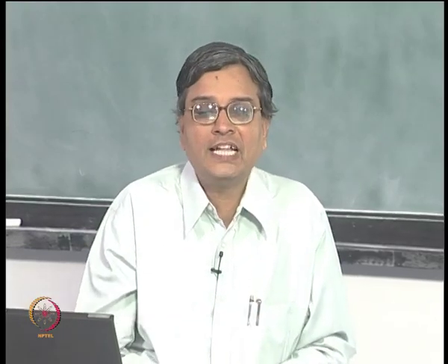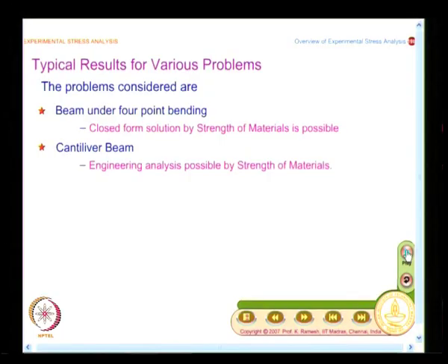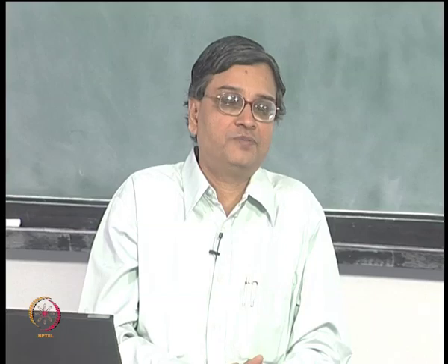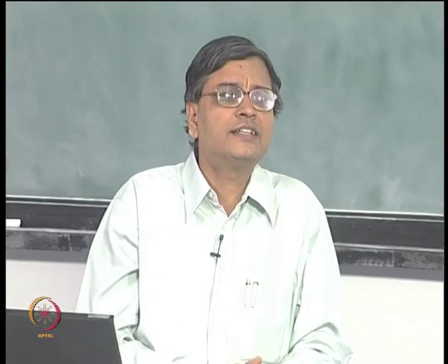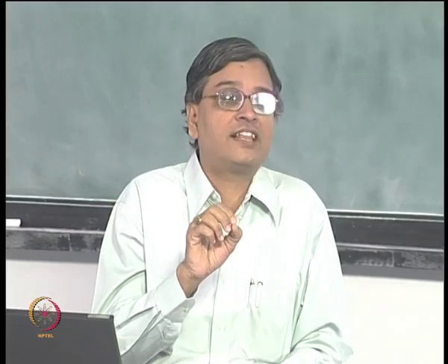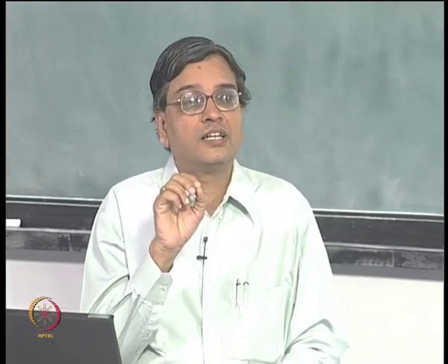Okay. Then the next problem is cantilever beam. Why I have taken this is, see, in a cantilever, though you apply flexure formula and so on, you actually have shear which makes the planes not remain plane before and after loading. Because shear effects and bending effects are not coupled, still the solution for strength of material is valid, and that is why good books term this as engineering analysis of beam.